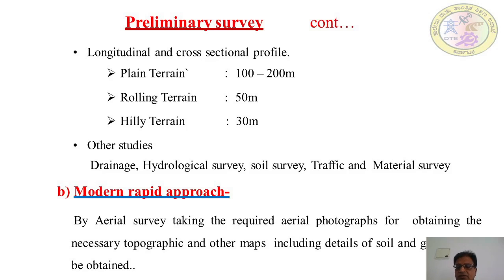Material survey. So in the material survey, what are the different types of material that are available at what distance? How much is the quantity available? Is that quantity sufficient for your road construction? All those things you need to calculate.